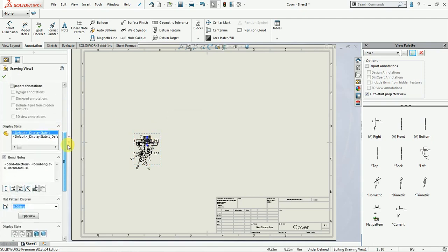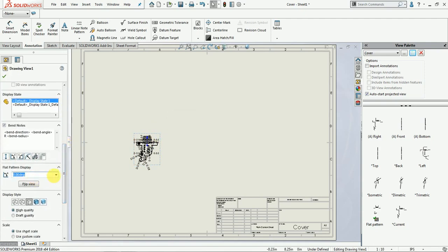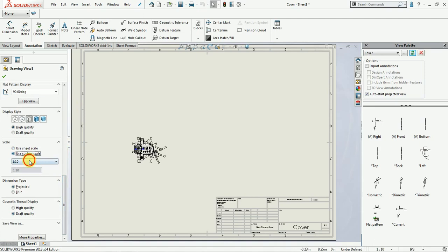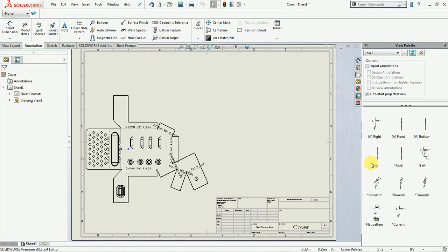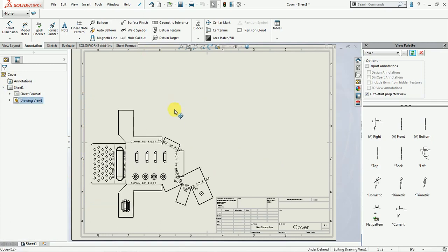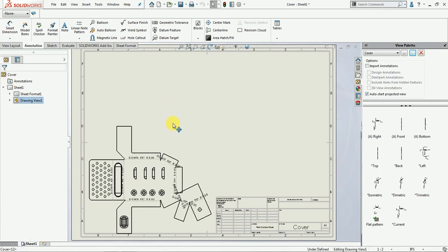I don't have to work hard myself, just picking and placing on the respective locations I need. Scales can be easily controlled, depending on the sheet scale as well as the custom scale. Here I just like to change my sheet to the custom scale at a 1:2 ratio.